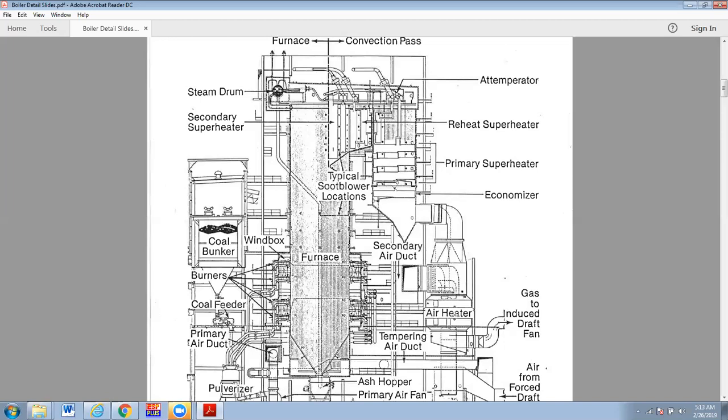These air heaters have seals on them, but the seals are not real good, and so we can leak air from the high pressure side, which is the combustion air coming in, because that's on the blast of the FD fan. The flue gas side is negative in pressure because it's being sucked out by the ID fan. So if the seals are not good, we will lose combustion air, and it will actually leak into the flue gas. One way you can determine the amount of leakage is to measure the percent oxygen in the flue gas before and after the air heater.